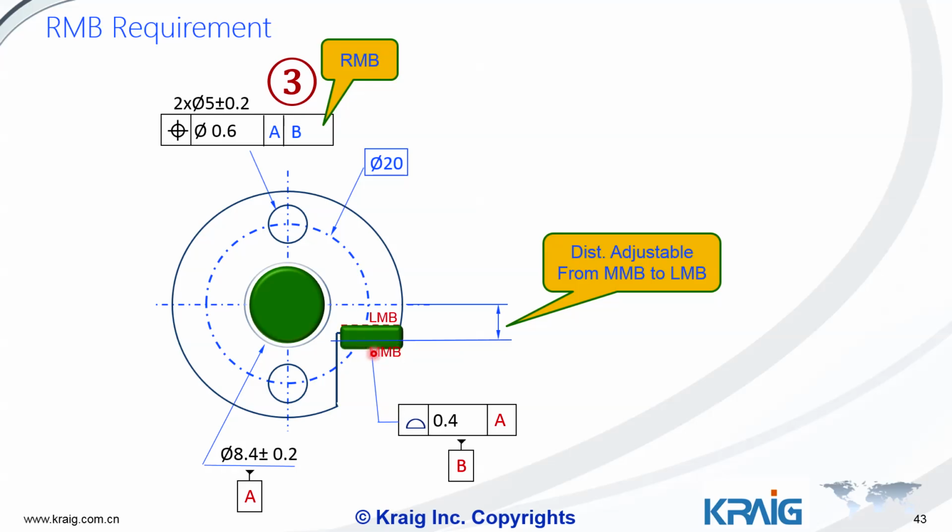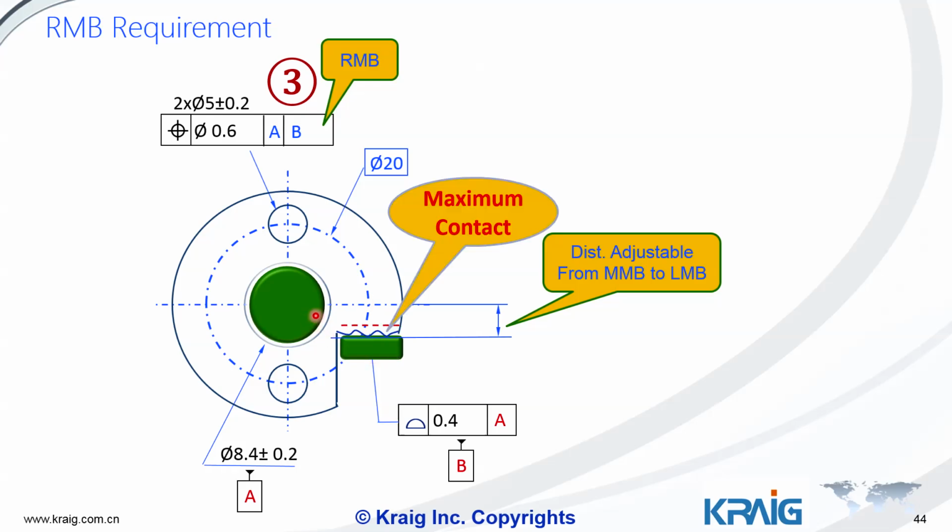The point is we can move up and move down unless the actual surface has the maximum contact with datum B. So you can see here, if there's nothing here, that means the gauge contact surface is going to move unless they have the maximum contact.